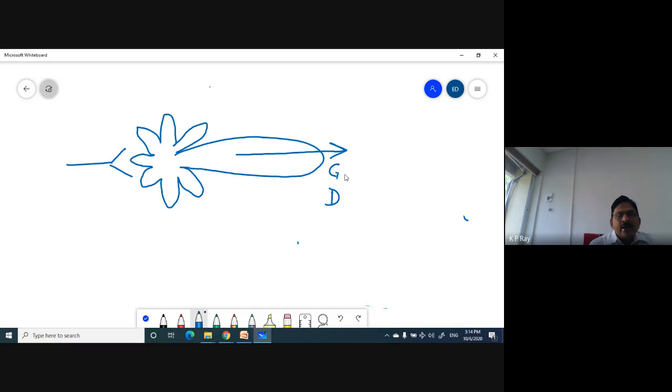same as the gain. So with respect to maximum radiation, if you try to find the half power point and then find this angle, then this is known as the beam width of the antenna. So you can consider this structure as a balloon, a three-dimensional balloon. So you will have beam width in two principal planes, like a balloon. If you cut in two perpendicular planes, whatever that 3 dB projection you get with respect to angle, that becomes the beam width of the antenna.